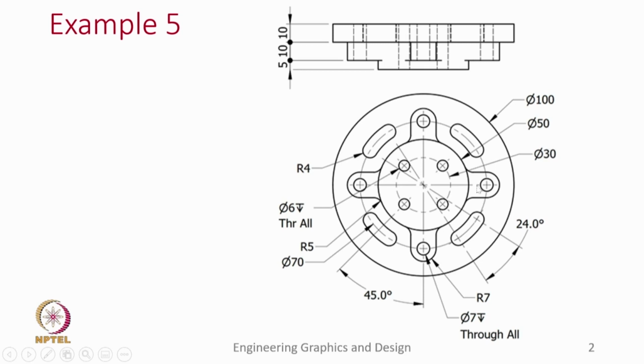And there are other features like the small circle, the cut and this feature, which if we notice closely, repeat 4 times, which means we can use the circular pattern because they are rotated about an axis at the center here. So, we will use the circular pattern to duplicate this 4 times. So, let us get started with the software.